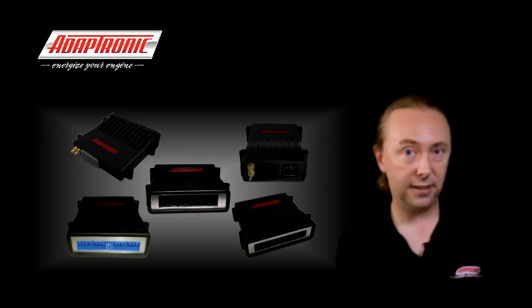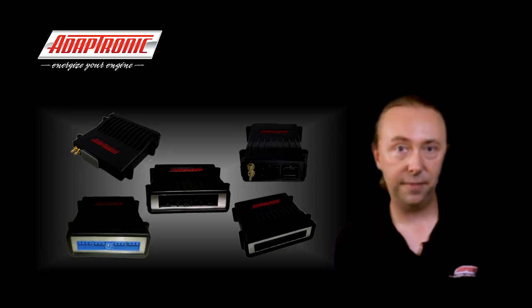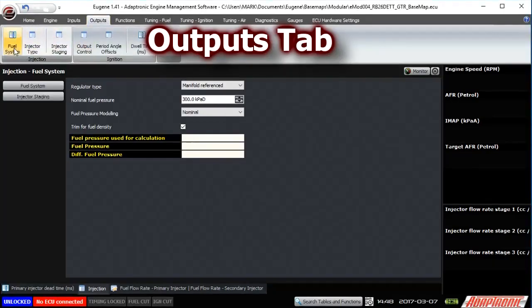So for a 4-stroke piston engine, you'd select 720 degrees, and for a 2-stroke piston engine or a rotary, you'd select 360 degrees. The next section we'll cover is the outputs, which is all the things that the ECU actually controls. Go to the Outputs tab and then select Fuel System from the ribbon. This is where we enter the basics of the fuel system.